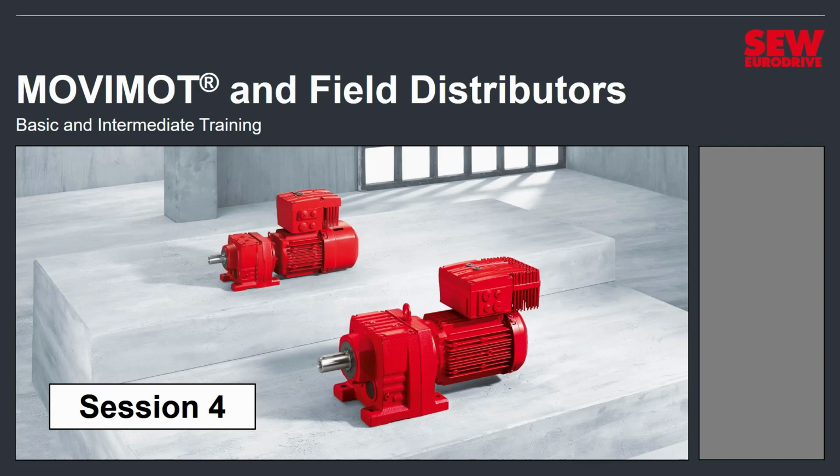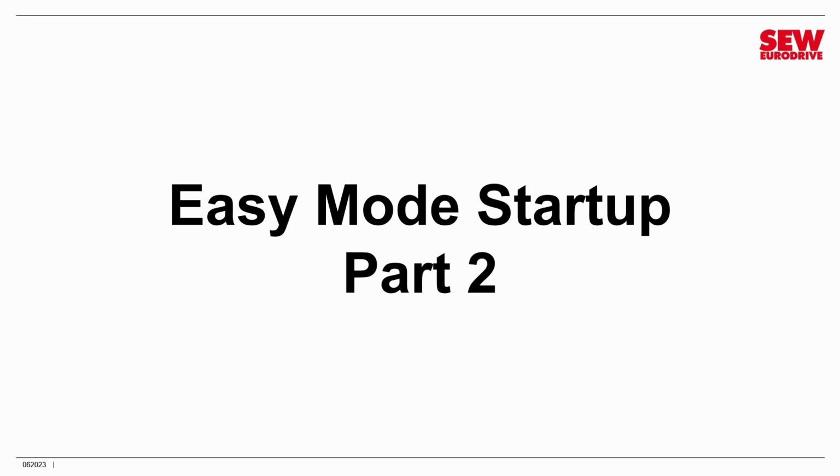This is Session 4. As you remember from Session 3, we were in the middle of an easy mode startup and we're just going to pick up where we left off and get that finished. So we're moving into easy mode startup, Part 2. In this part, we're going to set the various dip switches on the MOVIMOT control head. These configure its behavior. You'll need to set a few of these before your MOVIMOT is ready to run.